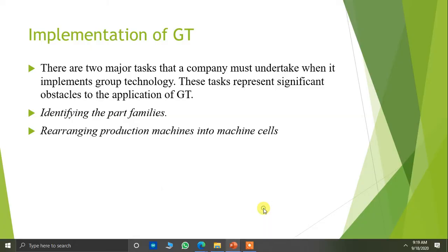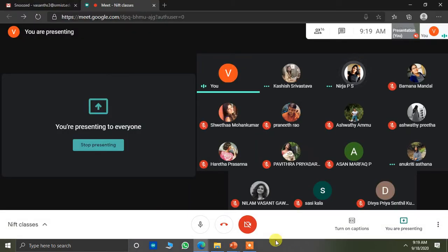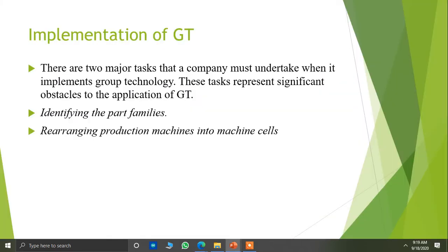Okay, I'll arrange the machines into some typical machine cells. That means, as I said, spreading and cutting together, or unrolling and spreading and cutting together. It is being done by 3 machines in 3 different places. Why don't I integrate them, put them in one cell? Thereby, your material movement time. You have a material movement as well, right? Guys, are you there? Yes, sir. We have. Okay, so can't I save time there? Can't I save space there if I integrate?